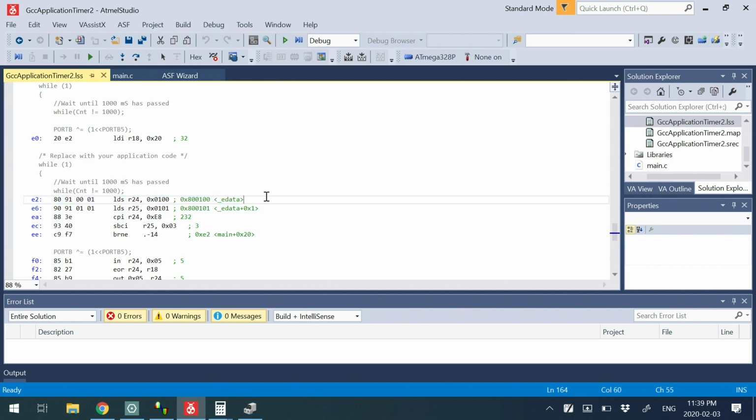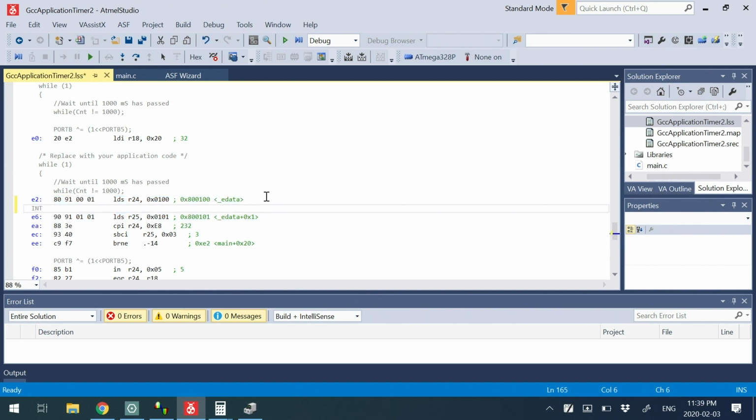But what could happen is in between these two statements, an interrupt could fire right here. And so this means that our value is changing as we're using it. So that's a little funky, right? Halfway through using the value, the interrupt fires.